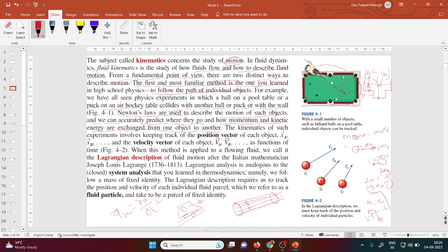So what is happening at that section? At that section, momentum is transferred because the faster main channel fluid particles try to speed up the adjacent slower floodplain particles, and the floodplain particles try to slow down the main channel particles. So at that junction, momentum transfer is happening. You can easily understand this with this concept.